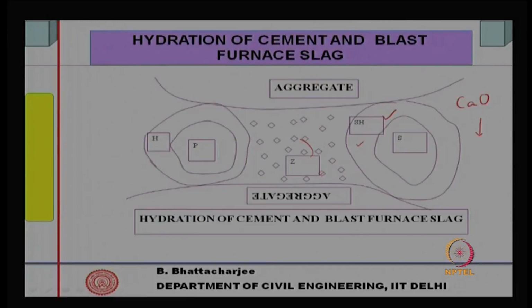Calcium hydroxide is a non-sealing precipitate and does not have bonding capacity, but CSH gel has. So, the excess silica in slag converts the calcium hydroxide into CSH, which is more of a bonding or sealing material. Thereby, it provides a better microstructure in terms of cementing property, and capillary porosity becomes lower.